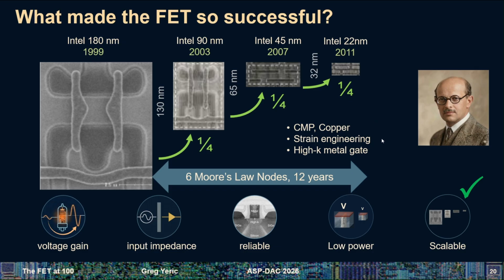And the way to buy back some performance was that some very innovative folks figured out you could physically strain, pushing or pulling, tensile stress, the silicon lattice and improve the mobility of the fundamental semiconductor. So we built in strain engineering, strain layers and such. We'll talk about that. It's more of a process thing, but we definitely want to talk about it on a device performance level as well.